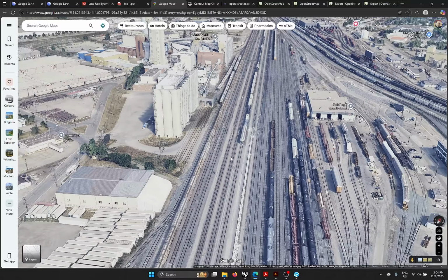So if I know it's about here and my 50 centimeter by 90 centimeter sheet of paper is about this ratio, I should be able to fit everything that I need within this crop region. So once I'm happy with that, I'm going to go over here to the share. I'm going to select the format to be a PDF, and then I'm going to set custom dimensions.